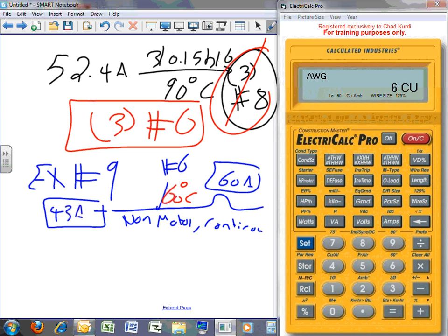Condition number 1, I have 60 degrees Celsius. And I decided to put these cables, that number 6, with another 9 conductors, 3-phase each, in a big fat 2-inch or 3-inch conduit. Can I put number 6 conductor 3-phase, 3 of them, with another say 9 conductors, number 4 and number 6, and size a conduit that carries all of them? I can, no problem. So I decided to have how many current-carrying conductors? 9.